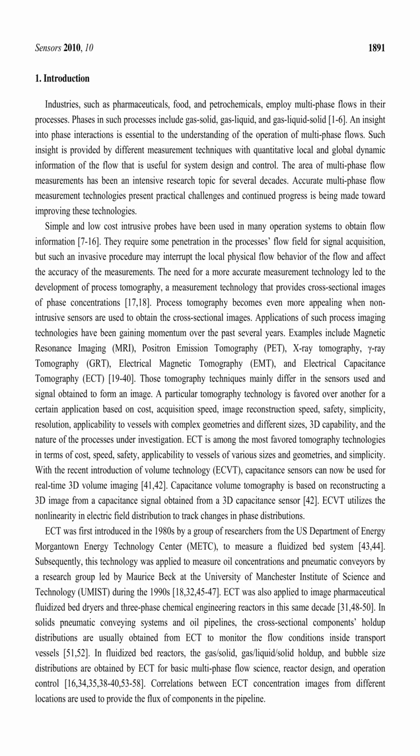The need for a more accurate measurement technology led to the development of process tomography, a measurement technology that provides cross-sectional images of phase concentrations. Process tomography becomes even more appealing when non-intrusive sensors are used to obtain the cross-sectional images.